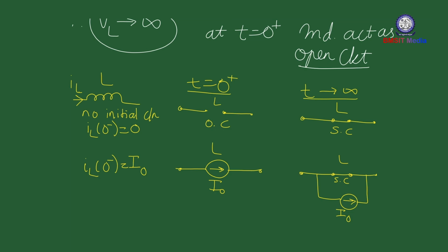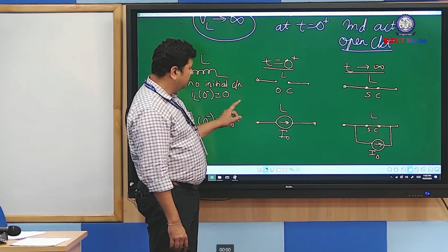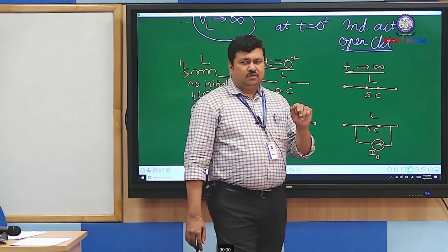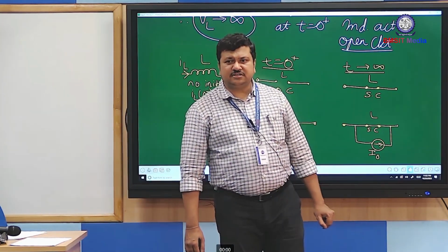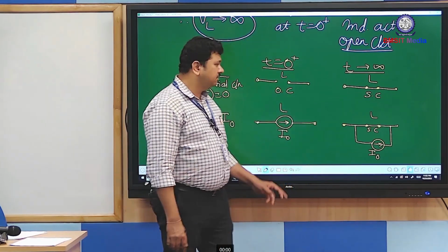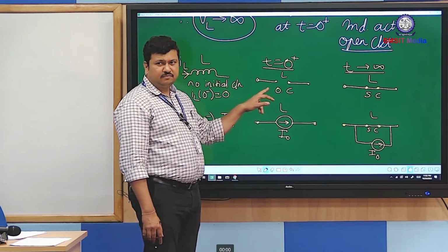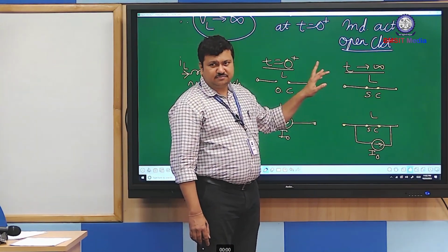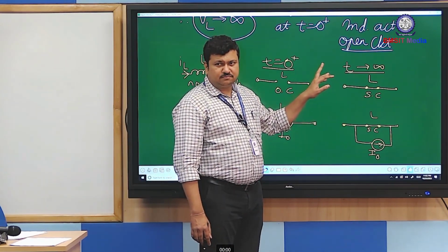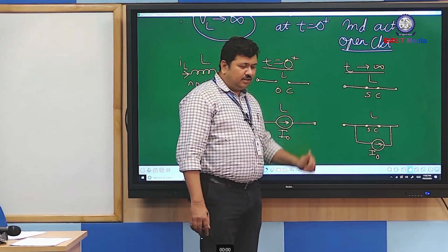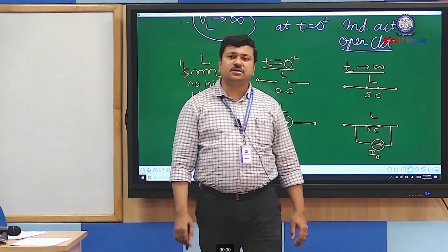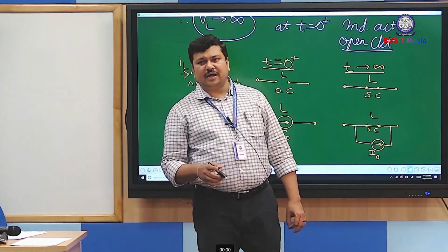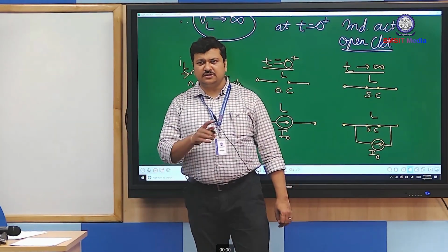So for the review, what I can summarize is, the inductor operates as an open circuit at the time of switching, and acts as a short circuit under steady state condition. The current in an inductor does not change instantaneously. That is the reason why the current lags behind the voltage if there is a change in voltage.